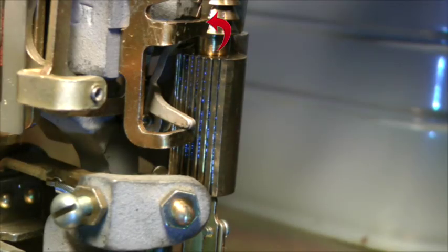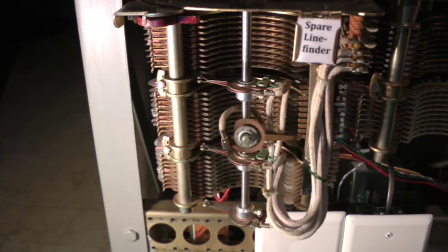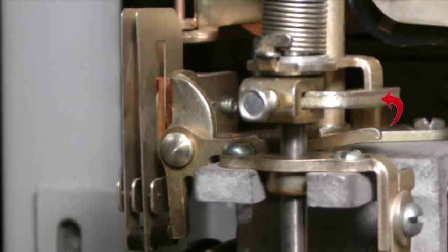With the leg of the stationary dog now residing in the vertical ratchet channel, there is no vertical support for the shaft, and so it and all of its attached apparatus drops down to its vertically normal position. As the shaft nears the end of its vertical drop, the normal pin strikes the off-normal finger, causing it to pivot to its rest position, which releases the vertical off-normal springs.